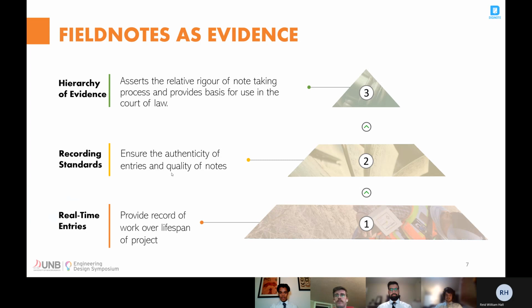Now, field notes are the only record of a field survey actually taking place. When discussing disputed boundaries in court, the Association of Canadian Land Surveyors provides a hierarchy of evidence that is supported by previous court judgments. The fourth and final level of evidence considered are measurements quoted by the original survey on a plan or in field notes. Although this evidence can easily be outranked by natural boundaries or original monuments, it nevertheless demonstrates the legal purpose that field notes serve.